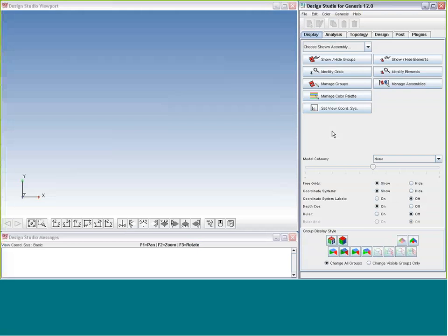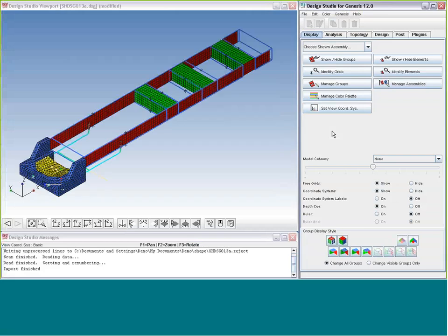To set up shape optimization, we need to define how the grids can move when design variables that define the grid location change. And we do that by creating what we call perturbations. A perturbation, you can imagine, is like a load applied to some particular grid, and that's going to be scaled by the design variable.